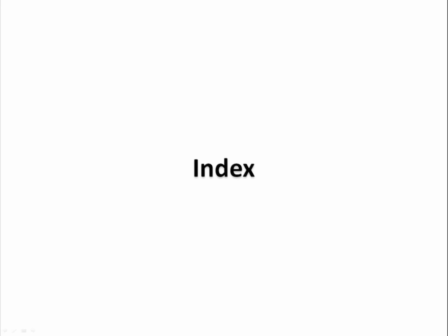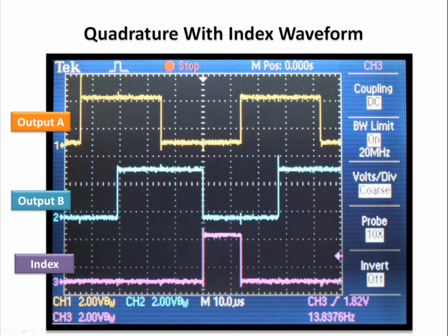So the next thing to consider when inspecting an encoder is if you require a third channel index. And the third channel index is just simply that. We have our good old output A and output B quadrature signals that we looked at previously. And now we have a third channel, which is a single blip or single pulse. An index pulse will essentially just be that. It's one mechanical location on the shaft rotation of your encoder, and it gives you one absolute position for the shaft rotation.